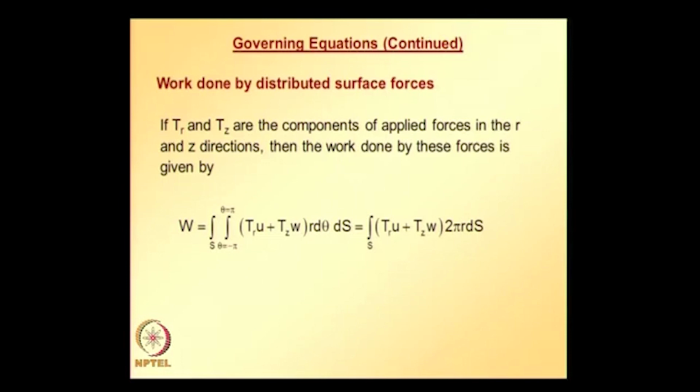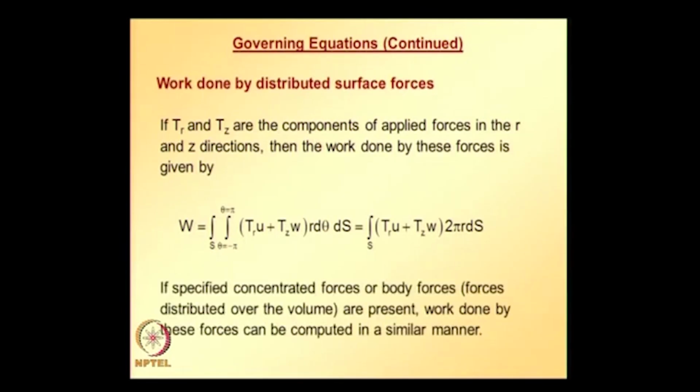We need to integrate over the surface area of the axisymmetric model, and for work done by the distributed forces, we need to evaluate a line integral along the side or edge along which surface forces are prescribed. If specified concentrated forces or body forces are present, work done by these forces can be computed in a similar manner. So, basically all this portion we covered in the last class.